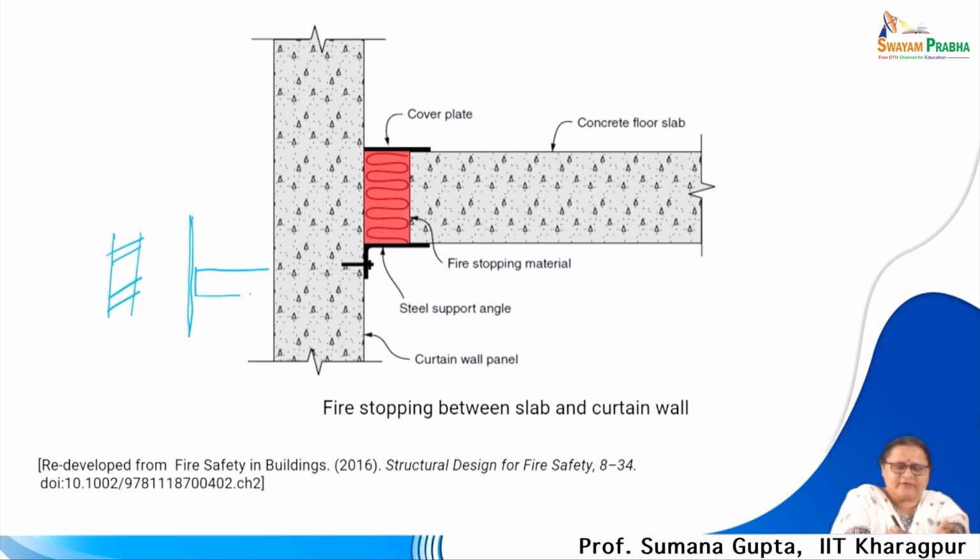So, wherever my floor slab is, this gap should be plugged in, and you can see here fire stopping material is there and it is held with a steel support angle, cover plate on top, so that it does not easily get exposed to the fire.